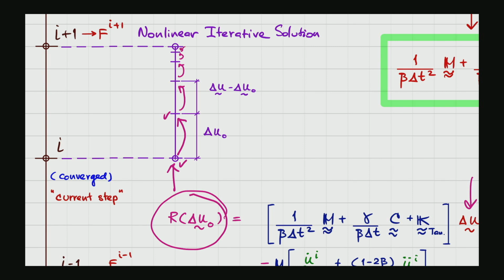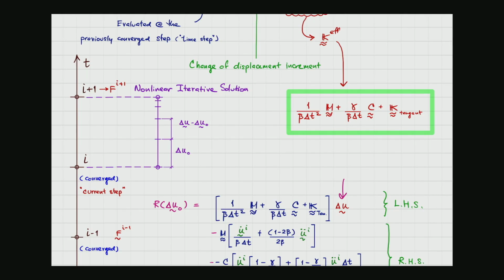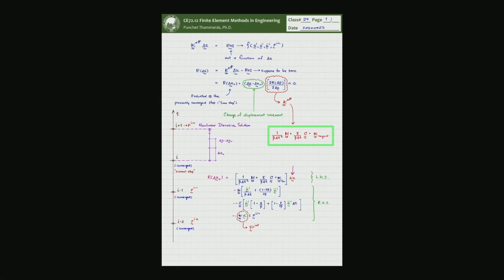So this depends on how easily the convergence is obtained. If the convergence is simple to obtain, if you don't put the program under a difficult time too much, you're going to need just a few, 2 or 3 iterations, and then you get the nice convergence. If you have 5, 6 iterations, that shows clearly that it is encountering a problem in the convergence.